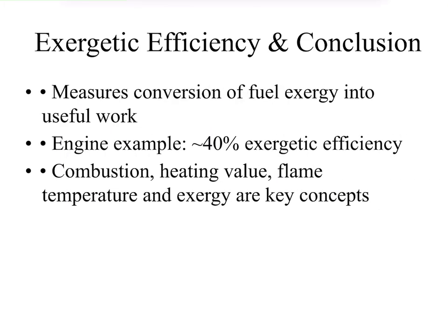Moving on is the exergetic efficiency and its conclusion. In conclusion, combustion is the foundation of many energy systems. Understanding air-fuel ratios, heating values, flame temperature, and exergy helps engineers design more efficient and sustainable thermal systems. Exergetic efficiency measures the conversion of fuel exergy into useful work. For example, 40% exergetic efficiency means that 40% is useful work.